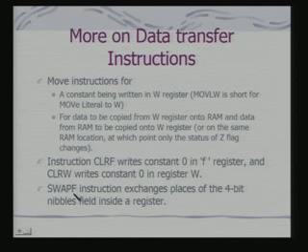Now, swap instruction, what does it do? It swaps the nibbles of a register. That means it exchanges, and this exchange takes place in a single instruction. Typically, when we try to exchange the values of 2 memory locations, we require a third, a temporary location.